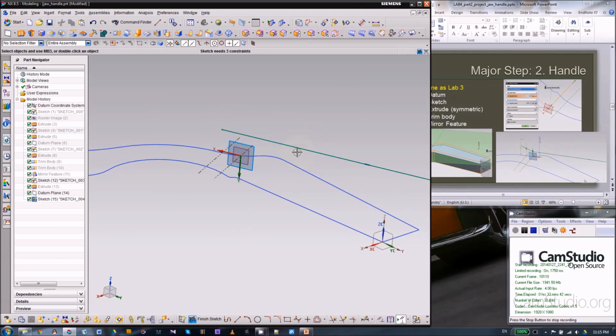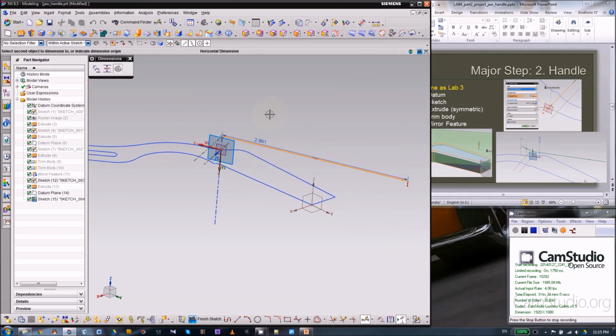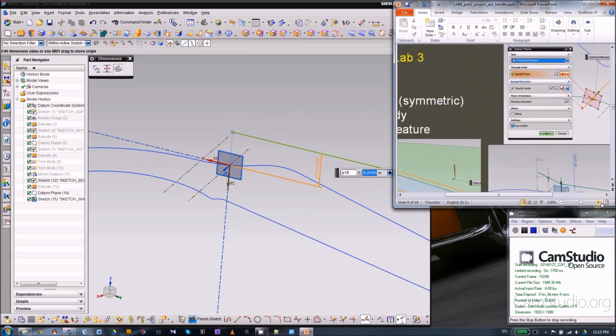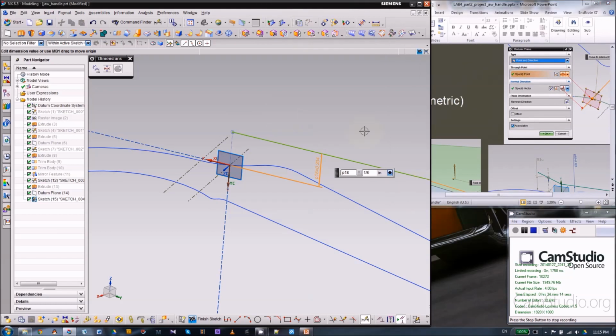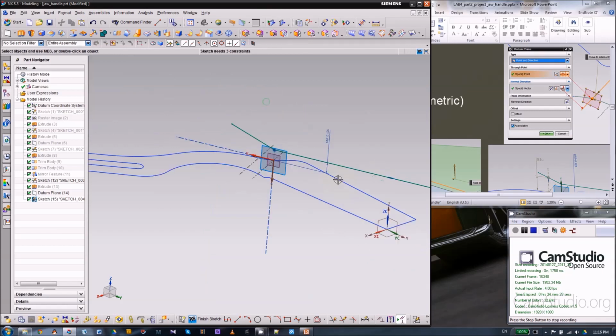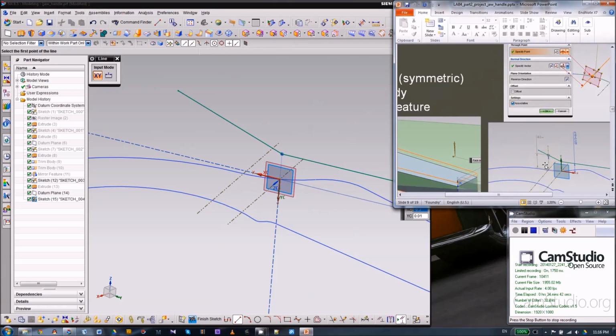Okay, and we want this reference line to be the start of the step. Like this here. So we'll put a constraint here, point on curve, the point on the y-axis. Okay, and a dimension between the line and the x-axis. That'll be right here. So zoom in, that's 1/8 or 0.125. Okay, and the step goes up, which is about like this. And we do want another dimension for this, so we can draw a reference line. So the dimension is actually from the projected point of this line to the intersection of this tilted line.